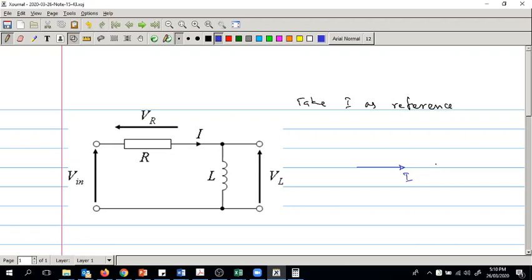Now you know voltage and current are in completely different two scales, so you don't have to draw this to a scale. I mean, you can't actually draw the currents and voltage in the same scale, but you need to draw all the voltages into a certain scale and all the currents into a certain scale. If the actual values are known, then you can calculate all angles and things like that using trigonometry. You can calculate the current values and things like that.